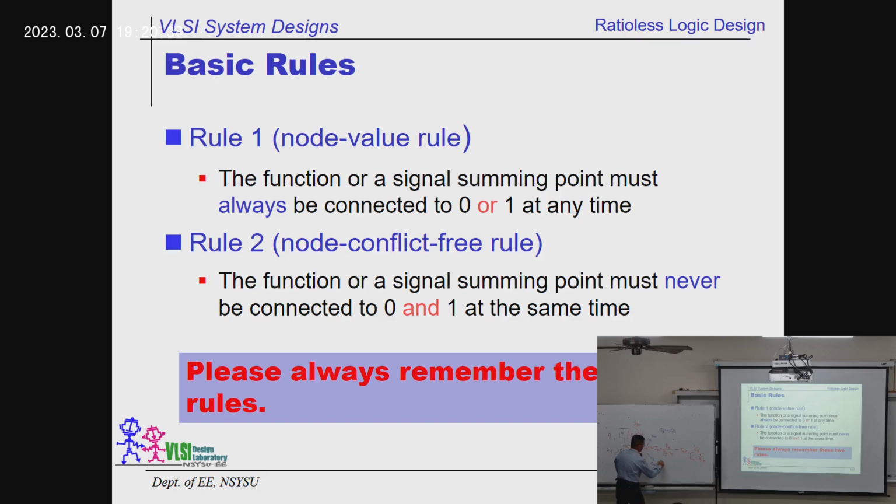If RB is very, very much smaller than RA, when RA is big, this term can be ignored, so we have something very small. So the funny thing is that the size ratio will determine whether the output is close to 1 or close to 0. So this kind of design is called a ratio design. That's bad. It's called a ratio design.